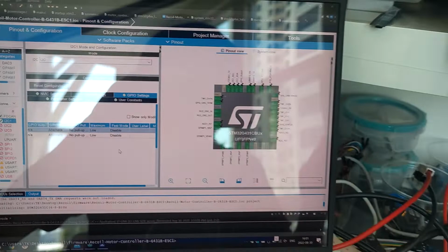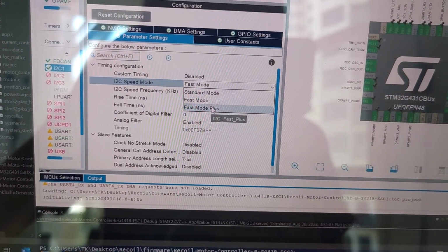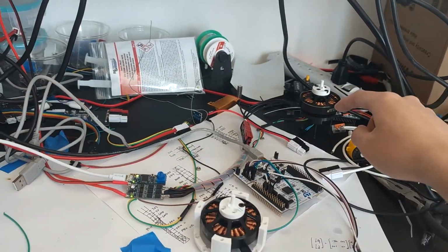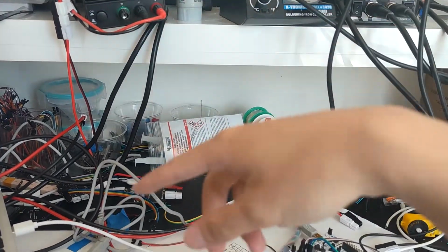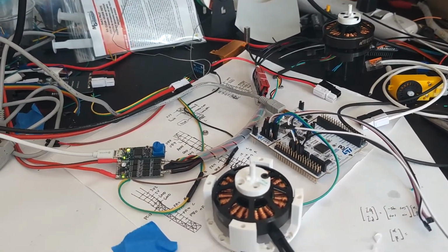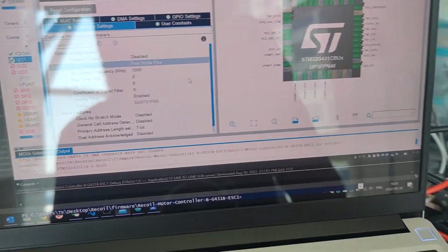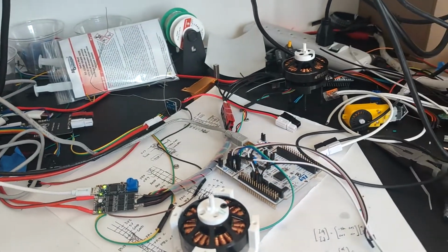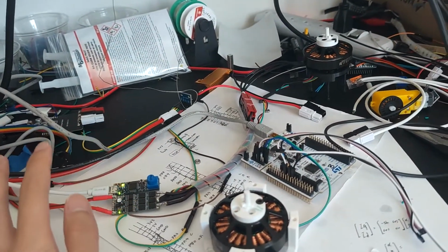Anyway, the issue is that when setting the I2C mode to fast mode plus, the encoder will stop working when there are current spikes on the supply VCC voltage. So that may be due to a signal integrity issue. The encoder is rated to run at fast mode plus, so 1 megahertz, but I just couldn't get it working. So during that dream, I thought of two possible issues.